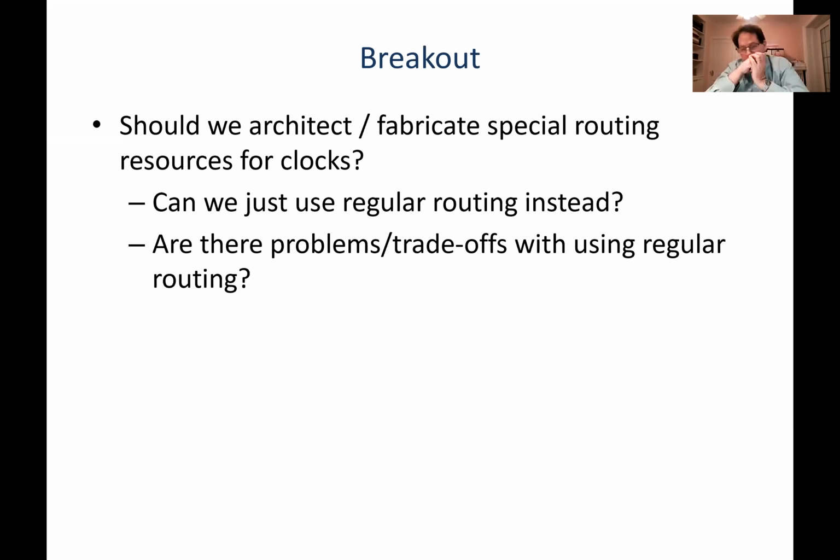Okay, so with high fan out, we don't need much flexibility, so we can be more efficient by taking advantage of the fact that clocks are known to be high fan out and probably need less flexibility. So we can save some area, so it makes sense. She says to manage delay, phase difference, fan outs. Camilo says they're not strictly needed, which is true. You could build an FPGA without any dedicated clock networks, but your timing would be hurt because you've got high fan out.